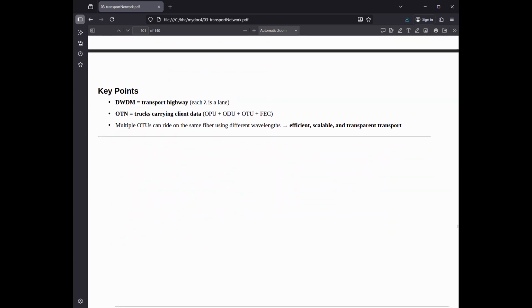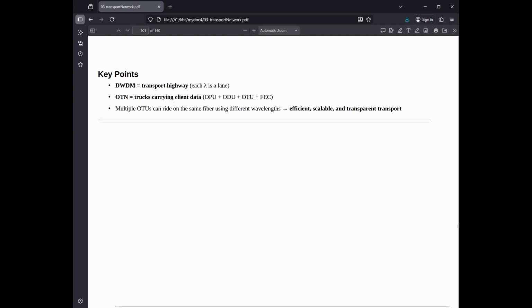Summary of the logic to visualize the flow: follow this hierarchy. Payload, the actual data, the cargo. OTN ODU/OTU, the digital management and error correction, the shipping container. DWDM wavelength, the specific color of light, the truck or lane. Fiber optic cable, the physical medium, the highway.